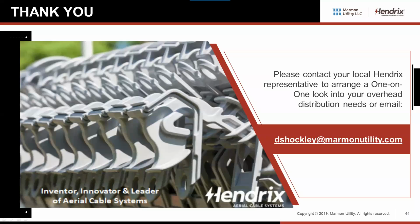Now, if a tree limb lays on it or comes down and is laying in the spacer cable, there's a lot of different variables as to how long that'll last before it'll fault. So what we commonly recommend is after a storm event or something like that, or maybe on a regular basis, clients will go out and patrol their spacer cable. I've had tree branches laying in spacer cable for over a year before it actually causes a fault.